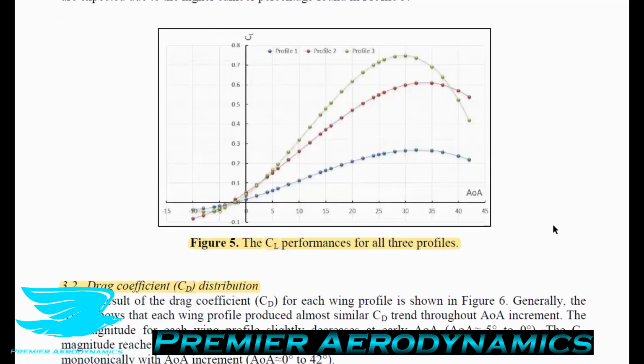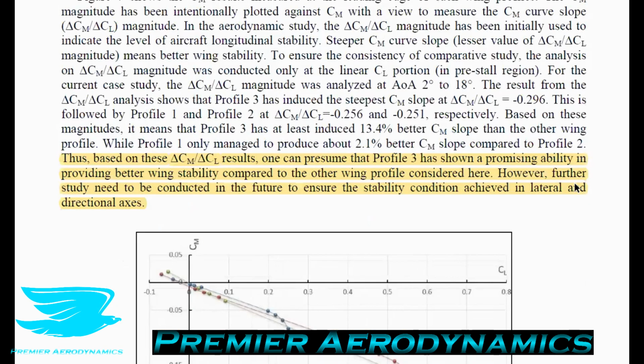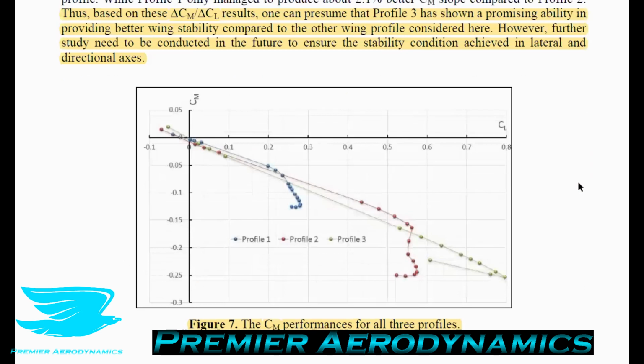So if we go to the lift coefficient graphs, we saw that profile 3, which was the most aggressively cambered wing, produced a maximum lift coefficient of about 0.75 at a Reynolds number of 100,000. For the NACA 0006, the maximum lift coefficient was about 0.7 to 0.8, again at Reynolds numbers of 100,000 as well. So they're very comparable, and that's the maximum that it produces. And the drag coefficients were about similar as well. So what this means is the Zimmerman airfoils are very good at producing lift at low Reynolds numbers, and they're also much more stable.